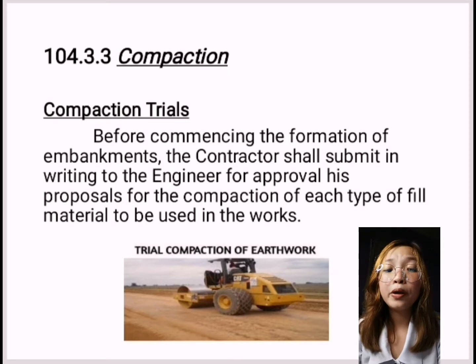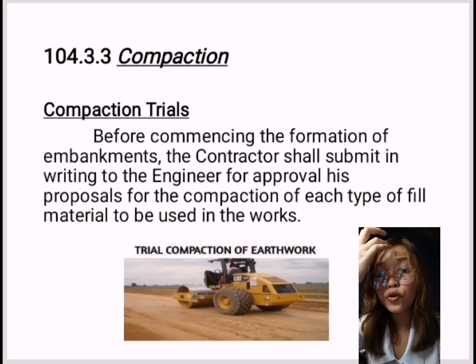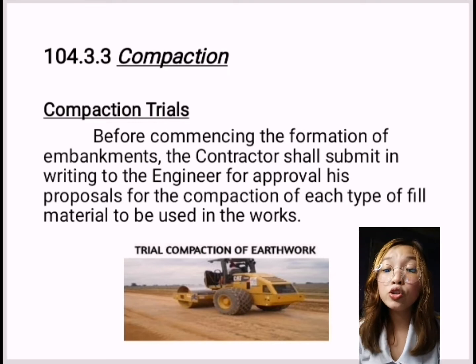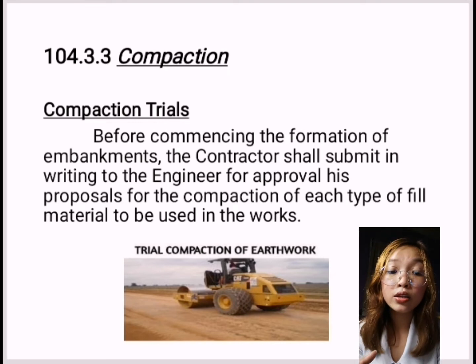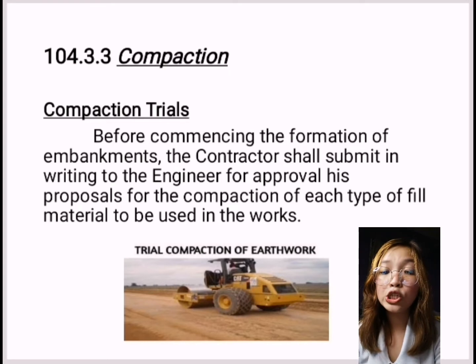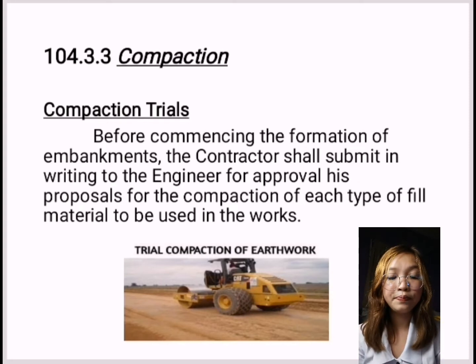So throughout the periods when the compaction of earthwork is in progress, the contractor shall adhere to the compaction procedures found from compaction trials for each type of material being compacted, for each type of compaction equipment employed and each degree of compaction specified.